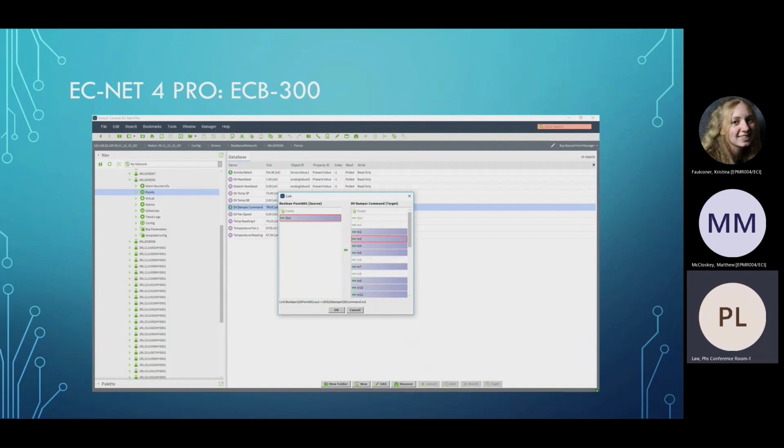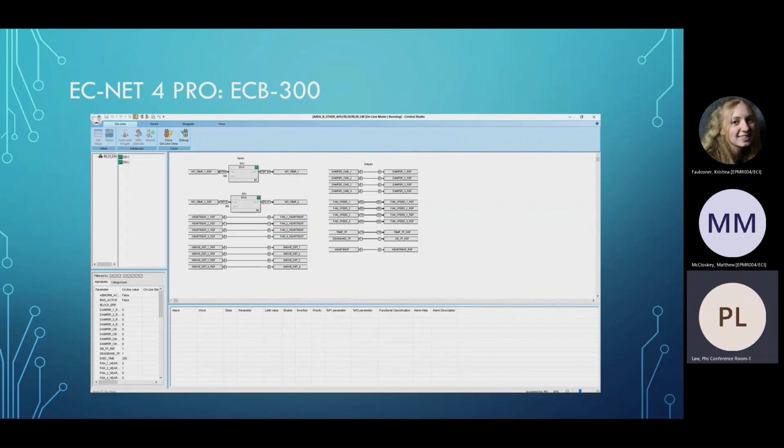And that allows the program to respond to a modbus port. And so what you do with that information is you just link the out to the N3, that's just to finish up the connection. And now we get to the point where you can actually start to manipulate Distech from Delta V. Now, if you make this a 1, that'll become a 1. That'll point to modbus register 601. That will point to the bacnet register for that particular device to be a 1, which will make that block in the program a 1, which will then respond to whatever we call the response.